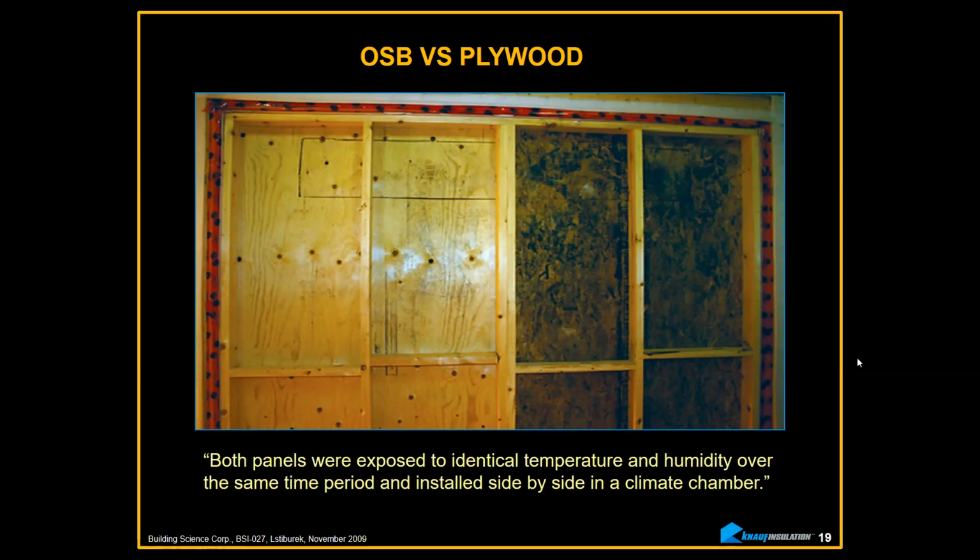And just the head flashing above windows, not doing the Tyvek right above windows. 99 times out of 100, the Tyvek's not done right above the windows. And so I'm glad you mentioned that. And just for all the inspectors on the phone or on the webinar, next time you go out to a house, just really pay special attention to that weather resistant barrier and how they're doing it. Go look at the method. There's a few different methods for a Tyvek install over a flanged window. Look through those installation instructions and you'll be surprised at how few times it's being done correctly in the field.